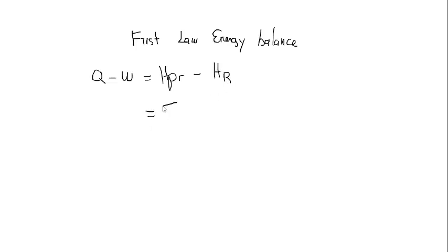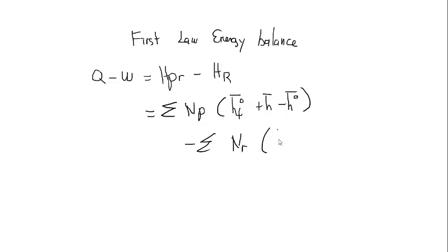This basically equals the sum total of the number of moles of product times the enthalpy of formation plus the sensible enthalpy minus the reference state, all that minus the sum of the same thing for the reactants.